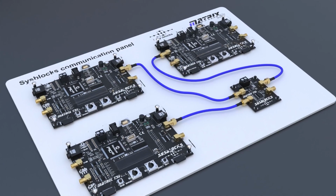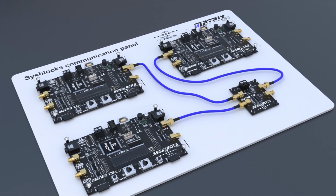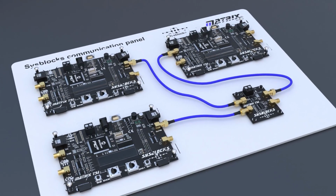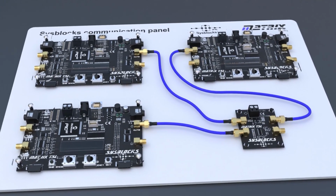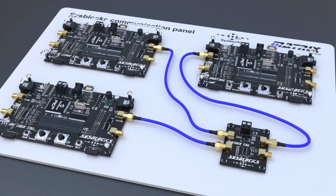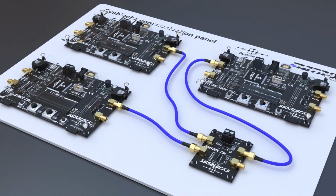In doing so, students understand the parameters of communication systems, including phase locked loop performance, signal to noise ratios, bit error rates, and the principles of digital radio techniques. The communication systems students investigate include PLLs, AM, FM, OOK, ASK, FSK, BPSK, QAM, QPSK and DSSS.